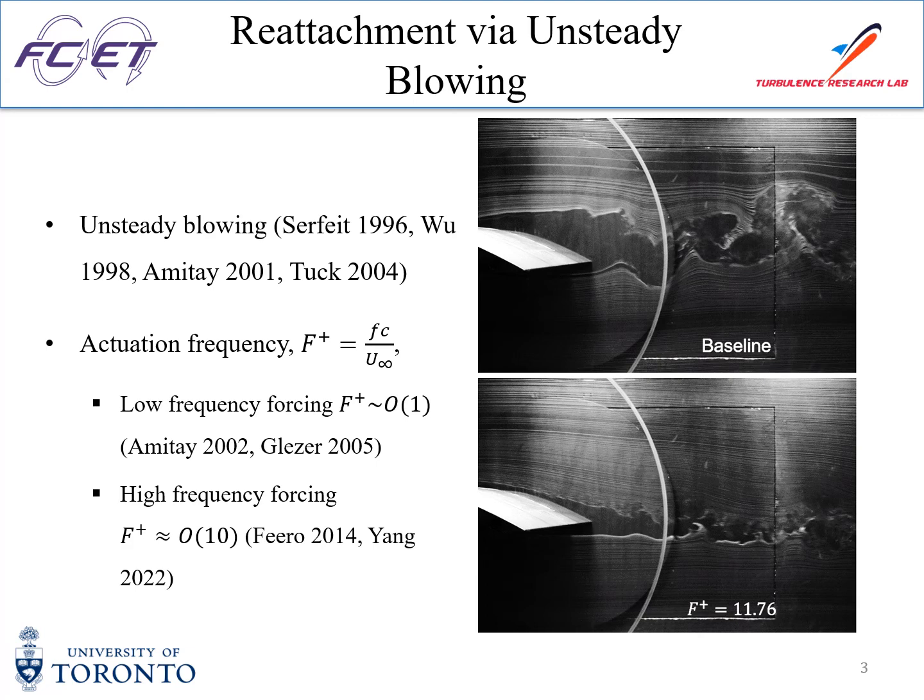The top is the baseline case, so no control is applied and the flow is separated from the airfoil, whereas the bottom one is a control case, where forcing is applied and the flow has been reattached close to the airfoil surface. Many works have shown that the actuation frequency is an important parameter of the blowing, which governs the dynamics and effectiveness of the reattachment.